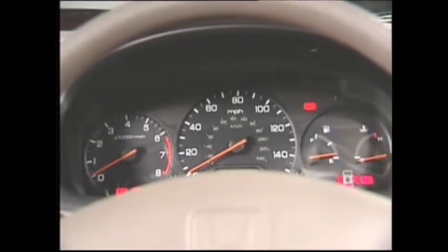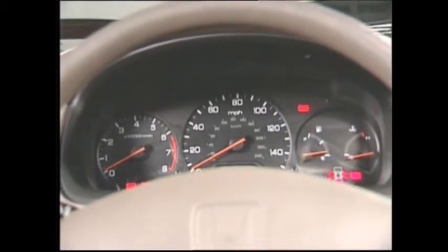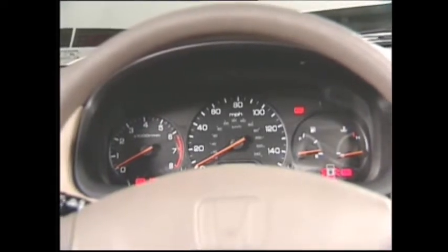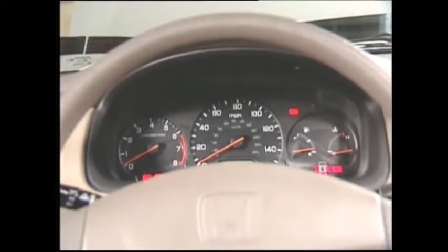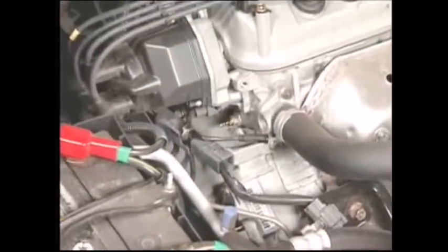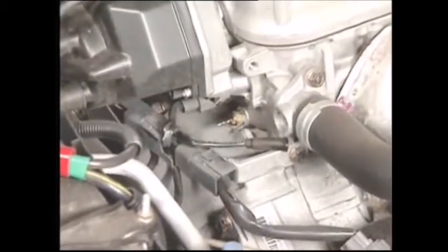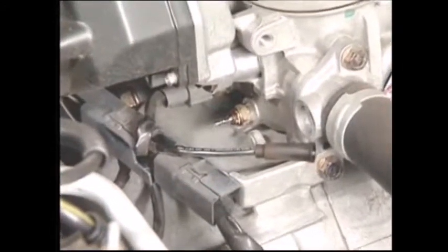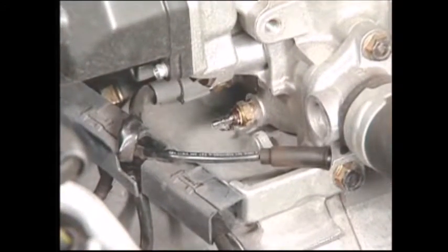Most vehicles use analog or needle-type dash gauges to relay information to the driver concerning items such as coolant temperature and fuel level. These electromagnetic devices rely on a variable resistance sending unit to regulate current flow in the gauge circuit. A faulty sending unit is the most common cause of an inoperative or malfunctioning dash gauge. Before replacing a sending unit, however, to correct a gauge problem, perform this simple test.